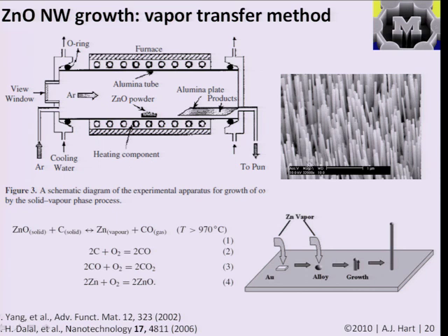They always grow along a certain axis dictated by the surface energy of the system. And you can do this in some cases without a catalyst, so just by this vapor-solid condensation method. And you can also do it using a catalyst, as we'll see later, or having a specific nanoparticle which has a higher affinity for what's coming out of the gas phase and then more specifically dictates the location at which the nanowire grows.